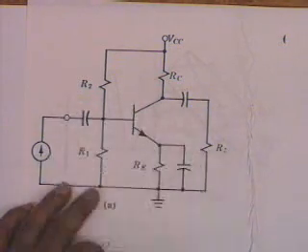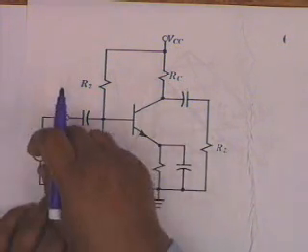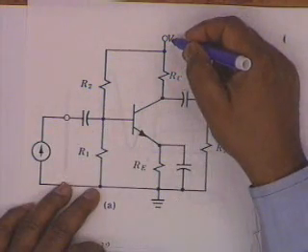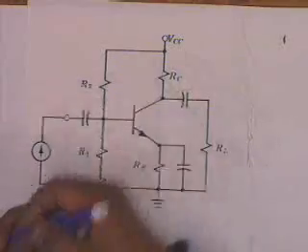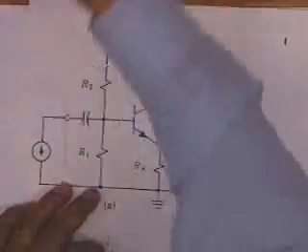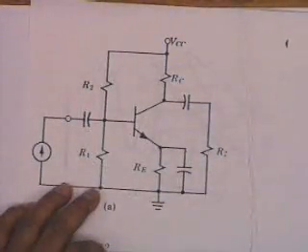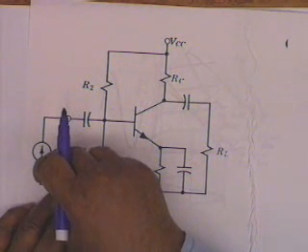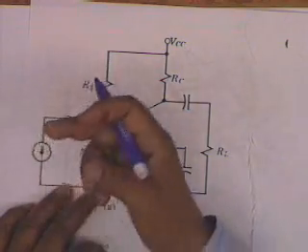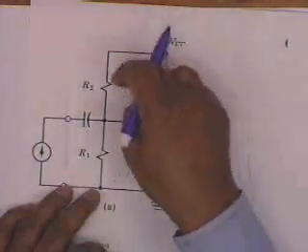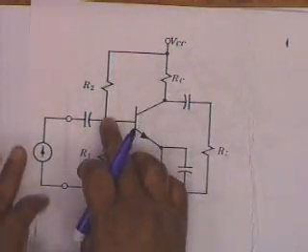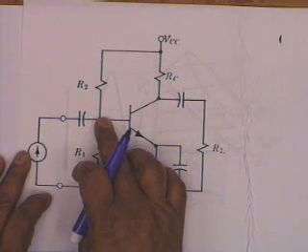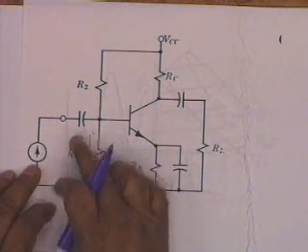For example, this could be a microphone or this could be from a transformer, and if this is a large DC, let's say 100 volt, then it might saturate the core of the transformer and the whole signal capability is lost. It could be an LVDT, linear variable differential transformer, whose core may be saturated because of passing of DC. So DC must be blocked from this signal source. This could be a microphone, as I said. Alright, so there is a capacitor here.